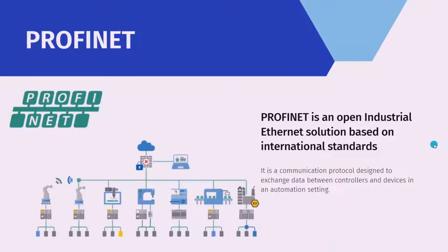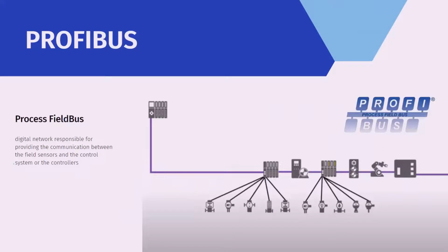wiring and engineering effort. Profibus is also a communication system. It communicates via a serial protocol behind which complex machinery is housed to transport the data reliably through an industrial environment. The protocol defines the message design, access to the network, and fault control. There are ASIC chips available that coordinate the entire protocol. This way, the product developer does not have to be involved much in Profibus to build the field instruments.